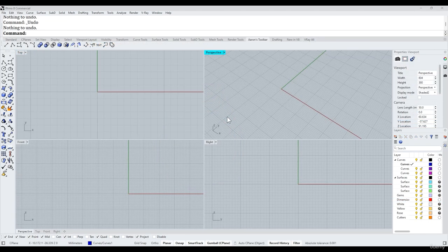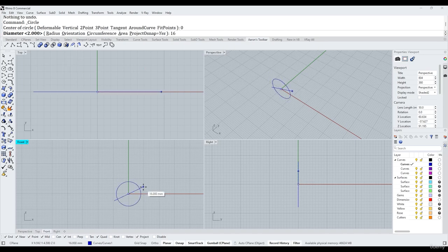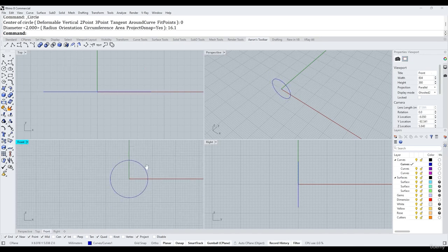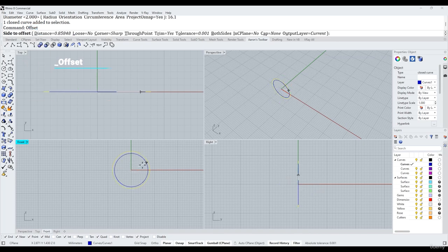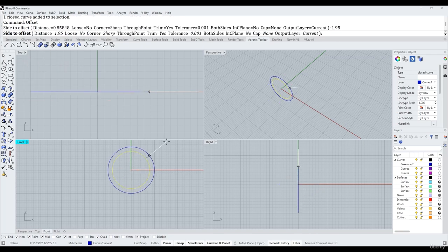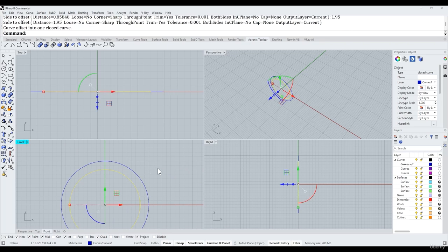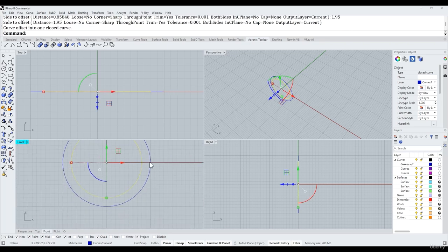First thing I want to do when creating a ring is start with our finger size. So again, I'm just going with a plain size L, which has a diameter of 16.1 millimeters. And again, I'm going to offset this 1.95. So that's going to finish up at 1.8 thick once we've trimmed back that 0.15 metal.